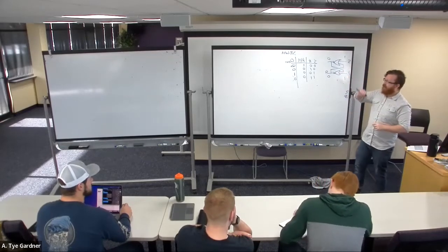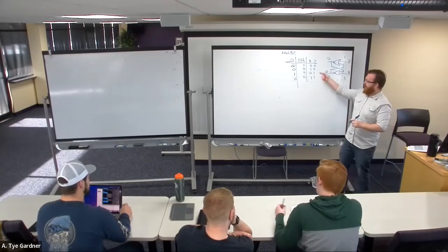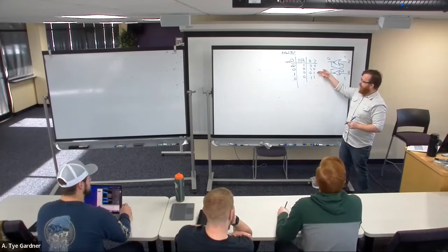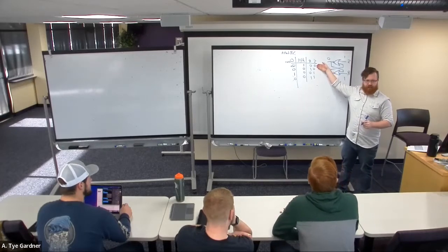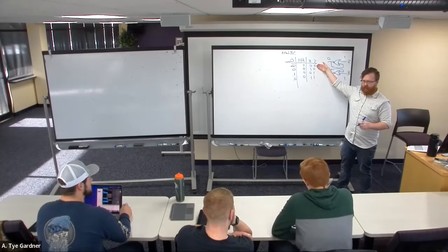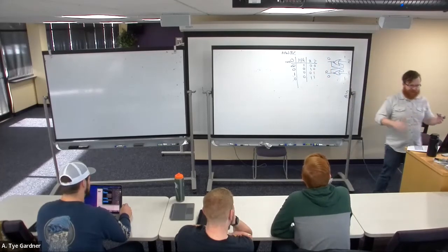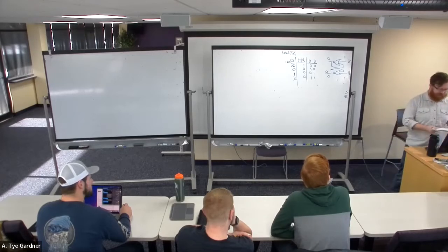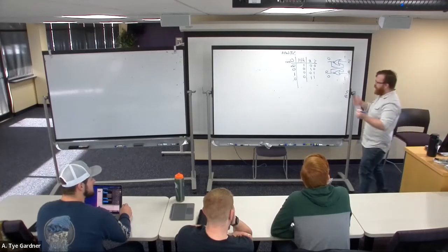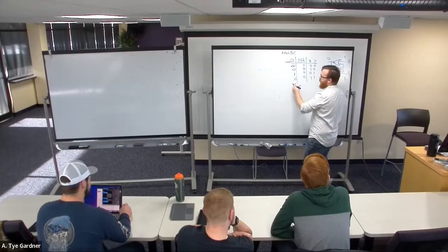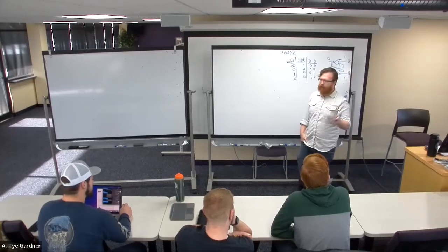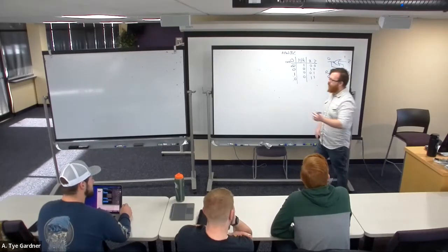But this is an SR latch, which just means I can reset it, set it, or latch onto the old value. I can hold what it used to be, which is an incredibly useful little bit of technology. Right now, we can start to remember something. We can draw this device. We give it a schematic symbol, write a block diagram, because we don't want to draw this all the time if I don't have to.